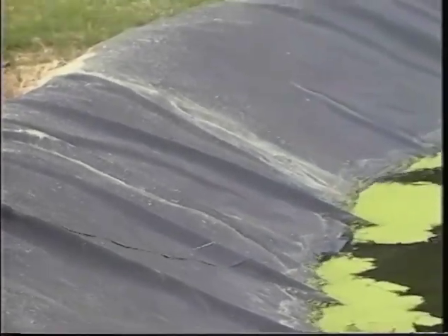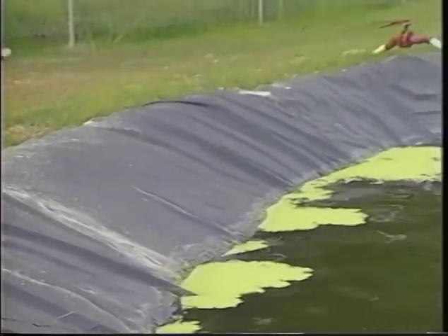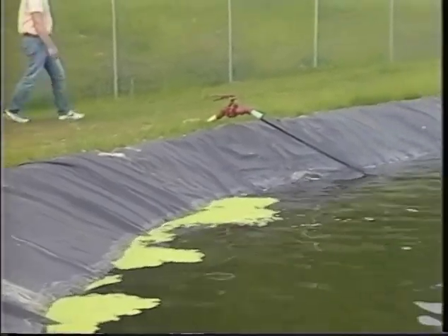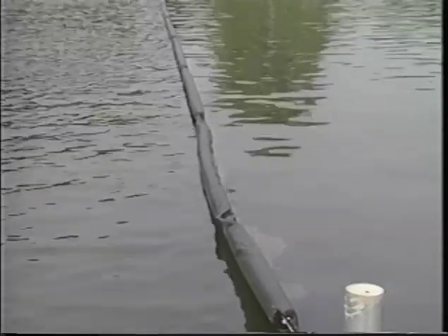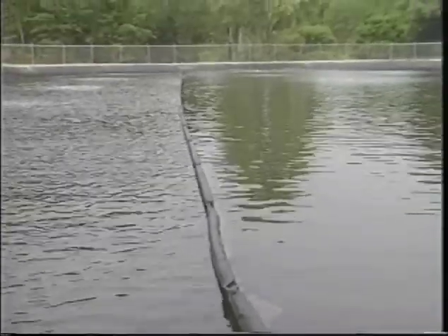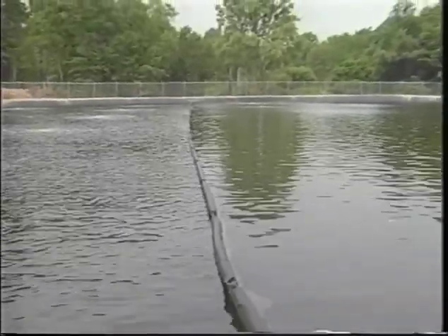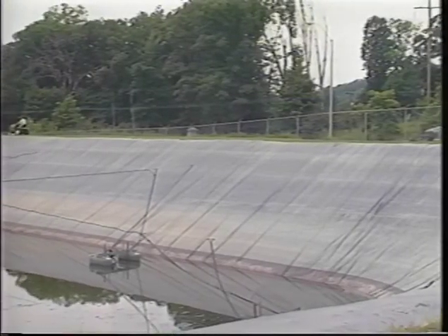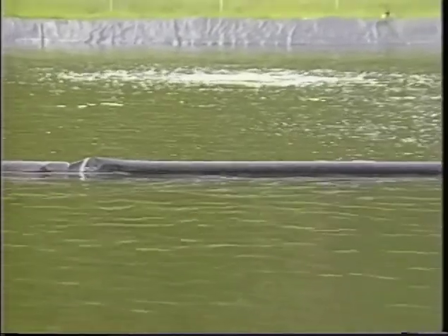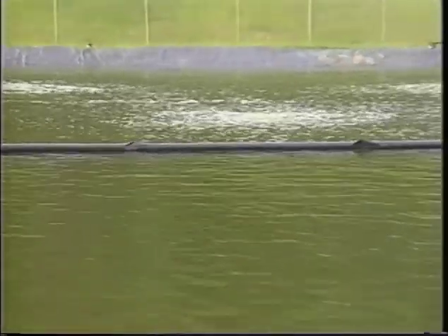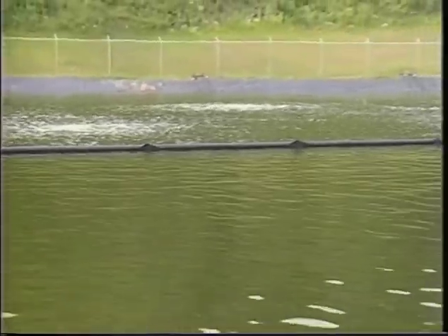Most lagoons built today have a synthetic liner to prevent contamination of groundwater. The lagoon depth is dependent on the design of the system. Lagoons may be operated in series of 2 or more and may be baffled accordingly. Some lagoons are built only for storage or flow equalization. Detention times of lagoons vary depending on design. A lagoon that has a detention time of 3 days or less will have little or no biodegradation of waste material.